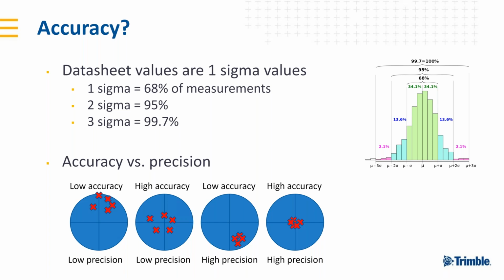You could also talk about absolute accuracy and relative accuracy. I would say absolute accuracy is how well your data fits into your reference data, which you know is well positioned. And relative accuracy could be something like, maybe you measure the height of a pole in the data and how accurate this is. So this might be relatively accurate, but could still be off in the location. So this is the world of accuracy we talk about.